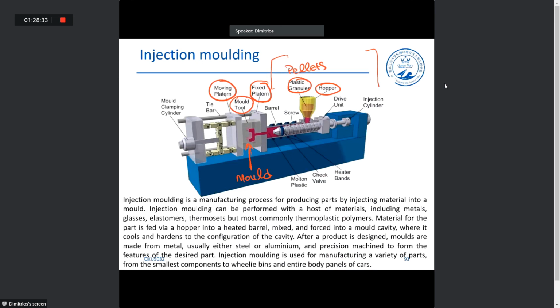And injection molding is a very versatile technique. Majority of the time it's used to process thermoplastics, though, as with extrusion. Okay. As I told you, it's very important to have very accurately fabricated molds, because any problems in the mold will result in significant problems with your final polymer materials. So the fabrication of molds for injection molding is one of the most costly parts of injection molding.